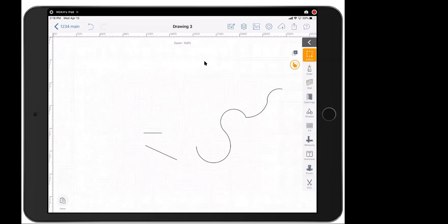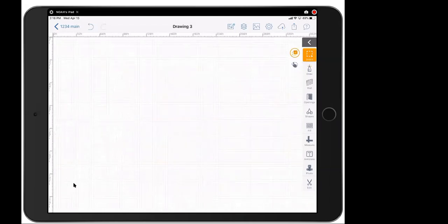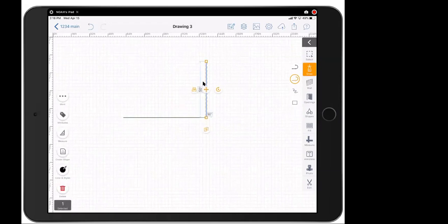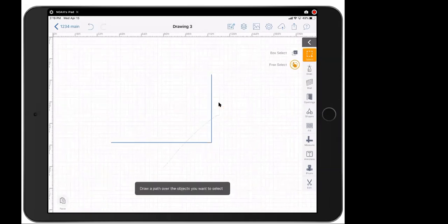I'm going to select all the stuff using box select and delete it on the left. Now, one of the things that's really important that you can do in ArcSite that isn't immediately apparent is you can permanently show these dimensions on screen. Obviously, if I click away from the line, I can't see how long it is, right? So depending on your use case, you might want that information to be readily apparent on an export piece like a PDF or PNG. So by selecting these lines, you can go to the More button on the left